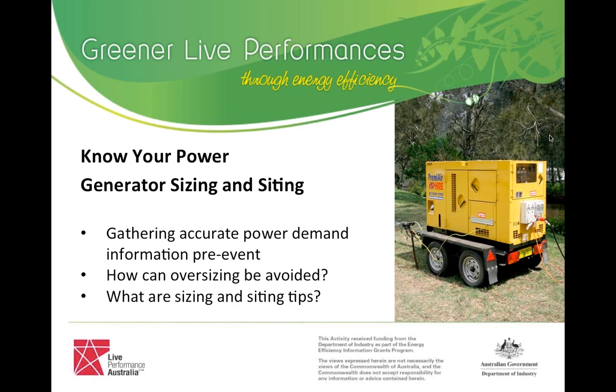If you have all that energy efficient equipment running on the generator and you're switching them off, you won't see that big a difference in the fuel consumption, unfortunately. It's probably at the starting point with the sizing where you get the biggest benefit. And obviously, if you go to a smaller generator, you're saving the daily rate of that too. So there's a cost saving involved with that too.